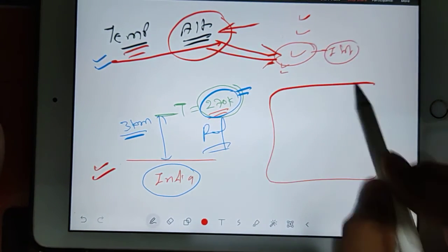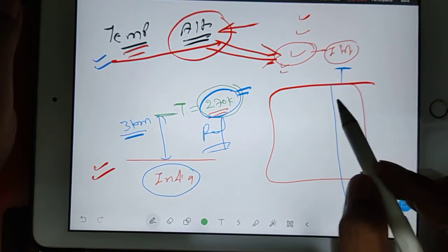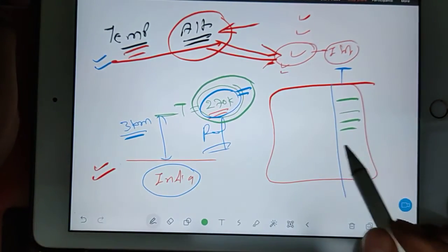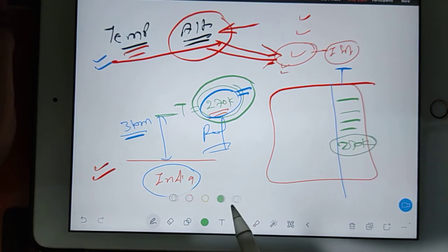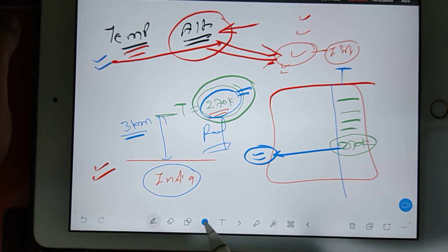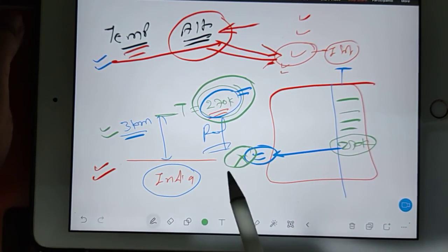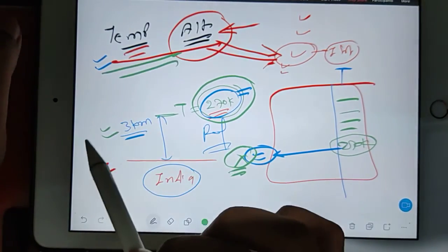So you have to open your ISA table and go to the temperature column. In the temperature column you check where this temperature of 270 Kelvin is given. In front of 270 Kelvin, what is the height mentioned? That height will not match the 3 km height. That will be some other height. That height is known as temperature altitude.